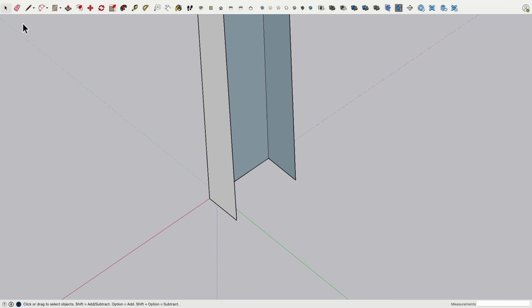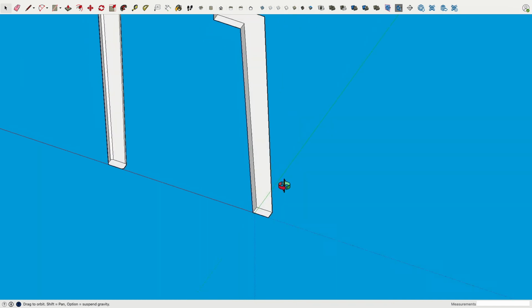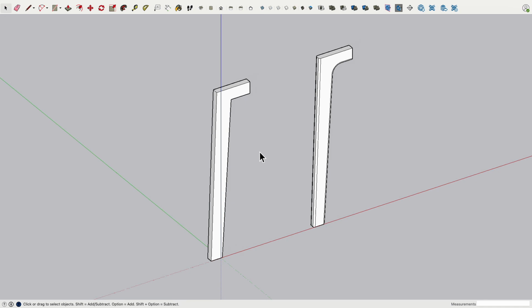So to fix this, you see I removed these two edges. That removes the two faces, but I simply put in a new clean edge and then it puts the faces back. That's actually really well solved in SketchUp, how it does that automatically. Very good.